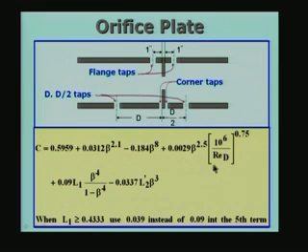So, let us look at the three devices in some more detail. The orifice plate. The orifice plate is essentially a tube with a small obstruction like this. This is a schematic, and I have indicated three different ways of measuring the delta P, locating the pressure taps for P1 and P2.